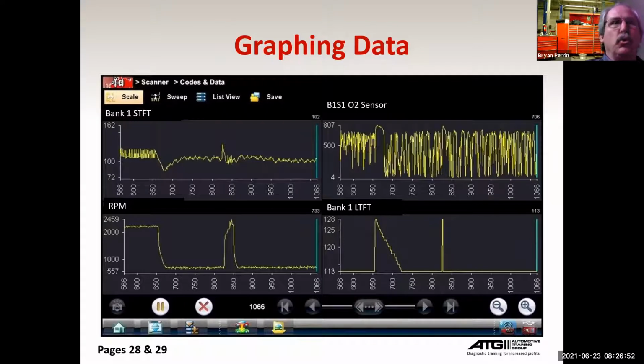I could use a tool that I do have and put a fuel gauge on it and look at the injectors and hit the button, and it turns them on for the exact same amount of time, and I can watch how much they flow. And that would tell me if the injectors flow the same, but my box flows a lot more current than the computer does. And in the past, it's hidden problems on me, so I don't really trust it. And it doesn't test the rest of the wiring on the computer. And then I thought to myself, wait a minute, I already have some great built-in tools here.